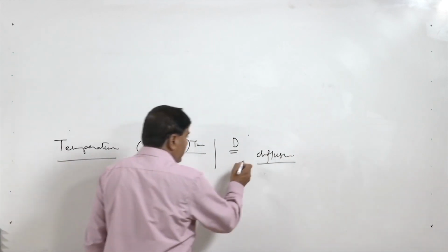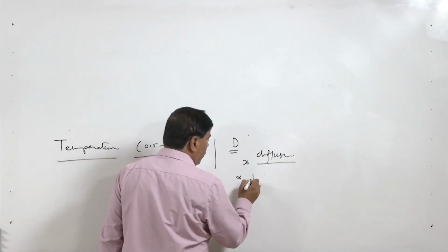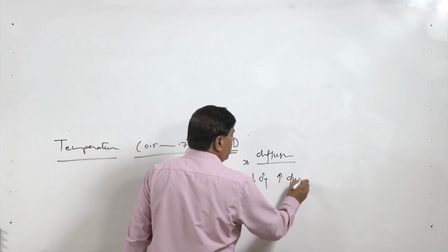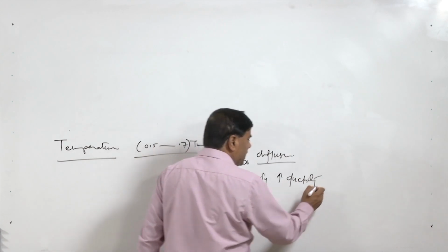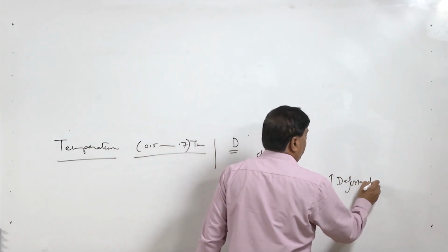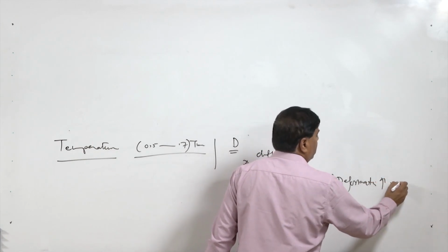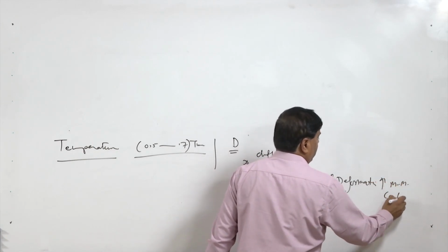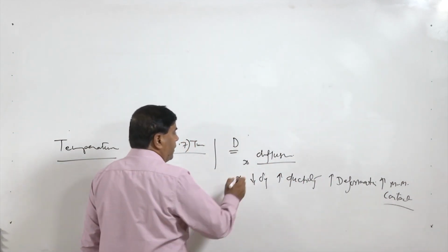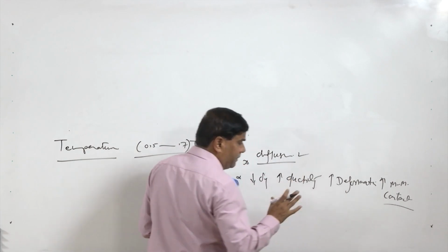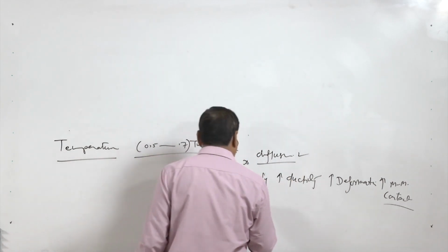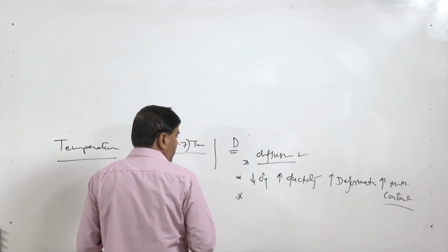Apart from facilitating the diffusion, temperature lowers the yield strength, increases the ductility of the material, and helps in surface layer deformation and increasing the metal to metal contact. So, this is important for completing the initial stage, and the diffusion is important for completing the second and third stages of diffusion bonding.